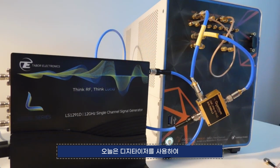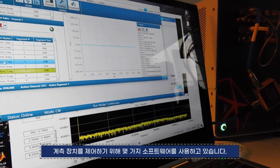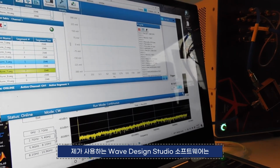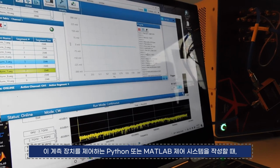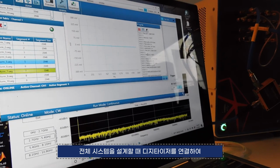And we're using the optional digitizer today on the Proteus arbitrary waveform generator to show some of the signals that we're going to generate. I'm using a couple of pieces of software today to control the instrumentation. Everything is controlled through USB, so it's very easy to set up. I've got my Wave Design Studio software here, which allows me to create waveforms and experiment with waveforms. At the same time, it also shows me the SCPI language that we want to use if we're writing a Python or a MATLAB control system for this instrumentation, so I can just directly learn from this software which commands I'll need when I get to designing the full system.